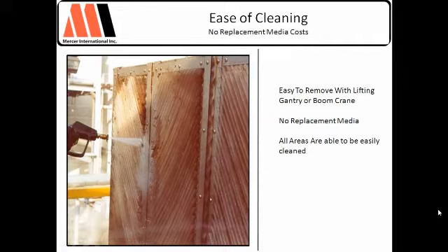Imagine the one you're either using or the one you're planning to buy. And imagine having a big two-fisted handful of coarse sand. Throw that into the coalescer, in the entry area, or throw it in on the top. What's going to happen to that sand? If 20 or 25% of that sand doesn't find its way falling out of the coalescer,